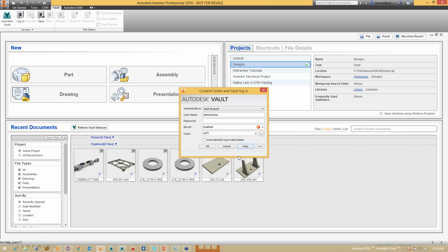Then when you're ready, what we typically recommend is creating a sandbox vault, and using it to test out your lifecycle definitions and your categories on non-production dummy data. You test it out in that sandbox vault, and then you say, yes, this is the process we want to implement, and you can go through and do that in the live vault. So I recommend going with Vault Pro as opposed to Vault Workgroup. Okay, good answer.